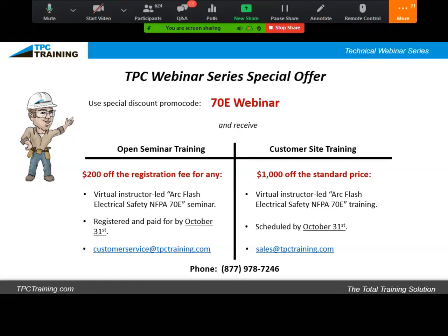That would depend on the condition of maintenance of the circuit breaker, and it would also depend upon how the breaker was manufactured and how we are operating that breaker. If it's a low voltage molded case circuit breaker, and we have performed everything that the manufacturer wants us to do for maintenance, and we've documented that maintenance, and all the covers are on, everything's closed, no evidence of impending failure, then operate the circuit breaker with no personal protective equipment. There's no issues if all those conditions can be met.